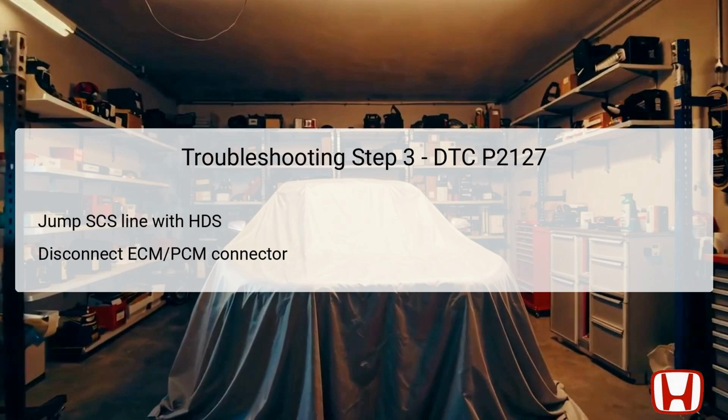The next procedure involves jumping the SCS service check socket line using the HDS tool. This function helps prepare the diagnostic tool for checking the connection status with the ECM or PCM. Following this procedure, the technician must disconnect connector A from the ECM/PCM, which consists of 44 pins.